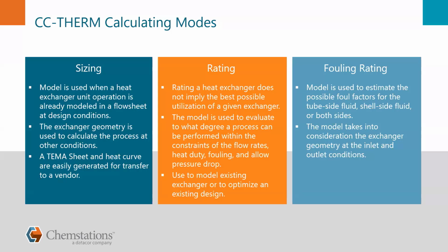So this fouling can vary from being very clean, though doubtful that it will be clean all the time, to a severe or extreme condition. So it could vary from, say, 0.001 to 0.005. So you are in between. What value would you actually consider? And would you be overestimating or underestimating this value?